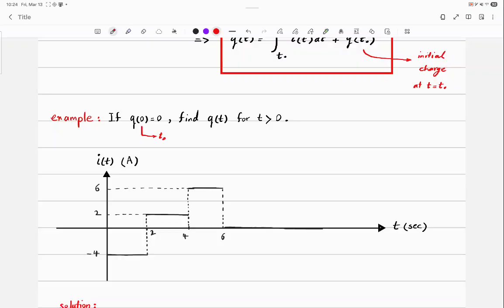If the current enters from the positive terminal, we actually discussed this, we proved this, you multiply I and V, and that will give you the power absorbed by the element. If the current enters from the negative terminal, you multiply I and V, and it will give you the supplied power. Okay? If you're confused, it means that you're normal.